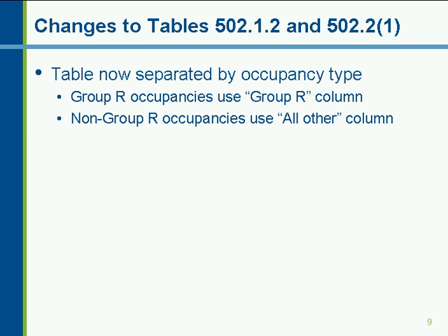One of the biggest distinctions that was made in the building envelope requirements for the insulation requirements for opaque envelope was the distinction between high-rise residential, which is 4-story and above residential, and all other residential, which are going to be office, retail, assembly, and those types of uses. And the column was put in there for all climate zones, and essentially the requirements for high-rise residential in the 2009 code are going to be more stringent than they were in the 2006 code.